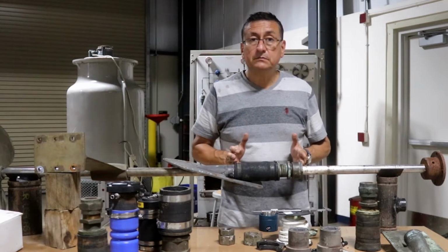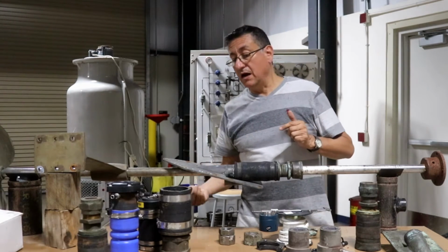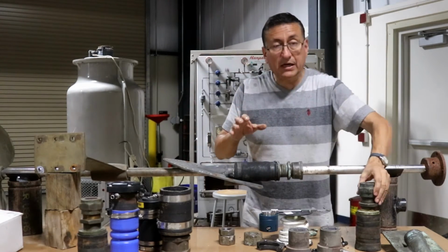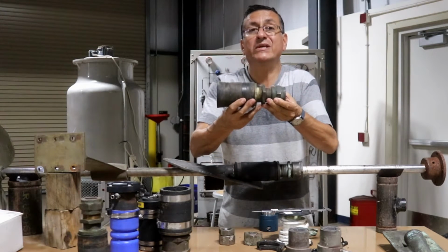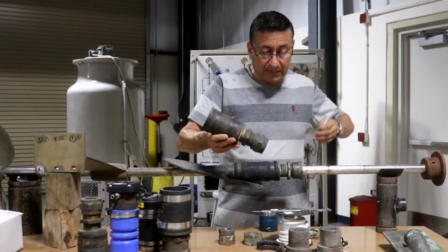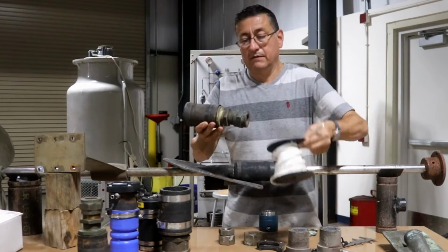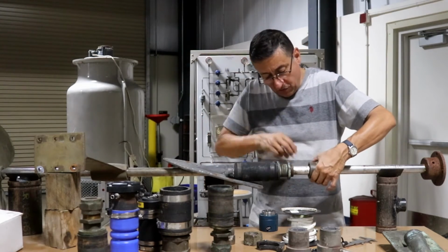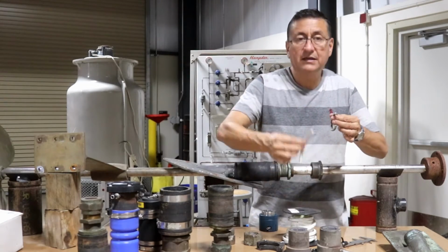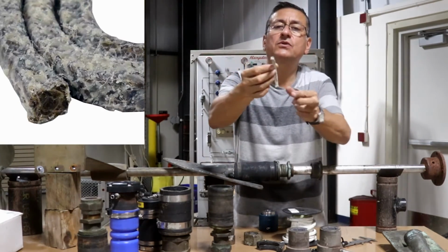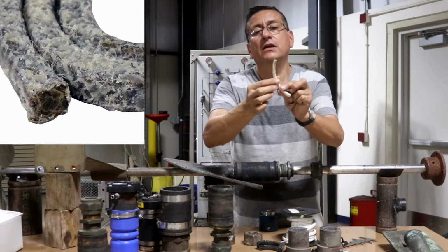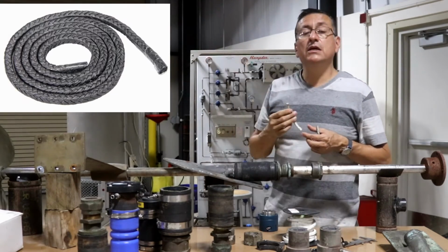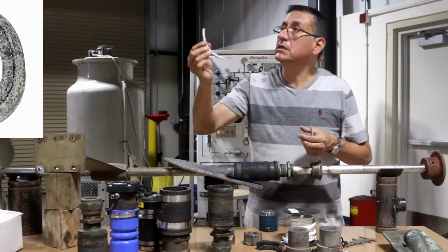The stuffing box is a mechanical seal that prevents the water from penetrating into the boat. If you disassemble it, this is the typical mechanical stuffing box with seal packets. When you open this element, you find the seal. The seal is a square. Normally it is a special fiber impregnated with graphite like this, or impregnated with animal grease, with fat.